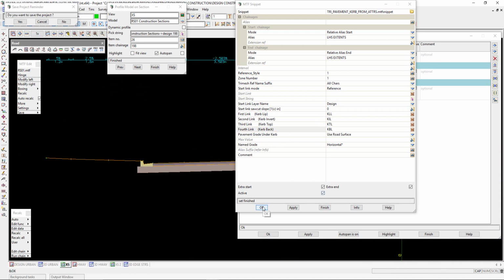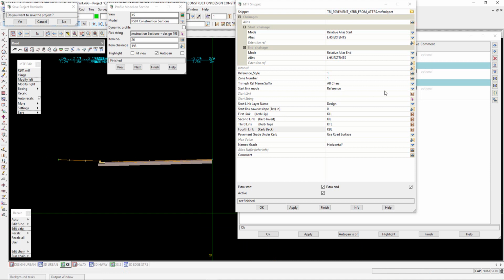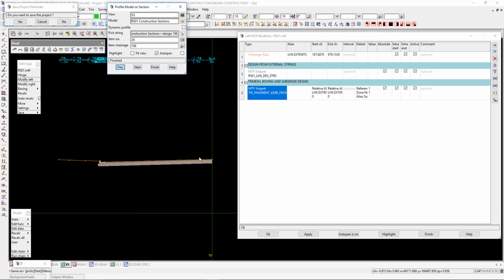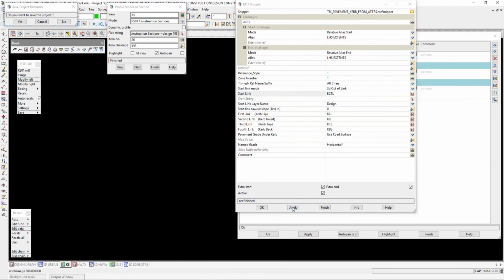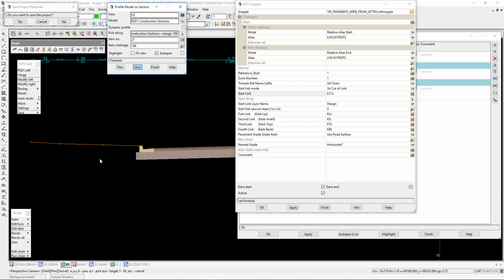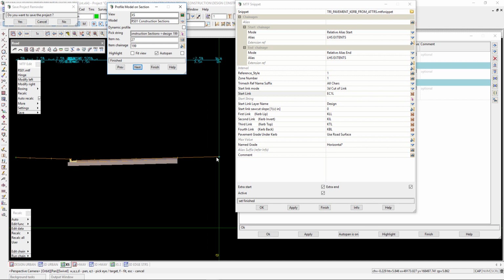So I was doing the curb profiles. If I go into this part here, again, if I go back to my reference style, if it was one of the lane lines instead, I could drop out here and pick 3D cut link. I go center mouse button and pick one of those, and again go apply. So this case is actually forming the part of the row profile, but only out to the lane line rather than the reference string, depending on what you're after.